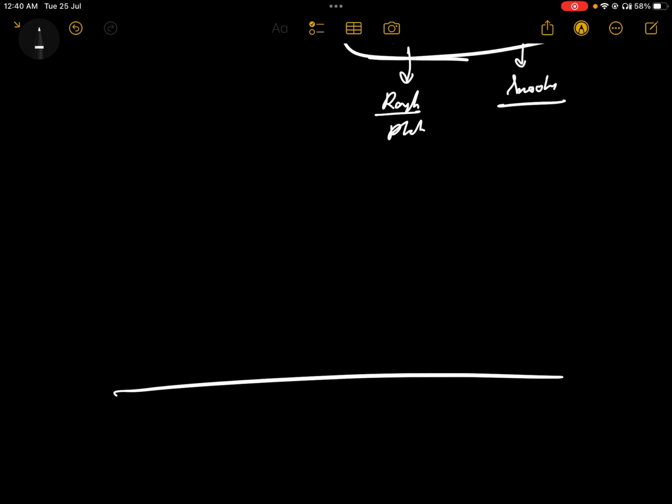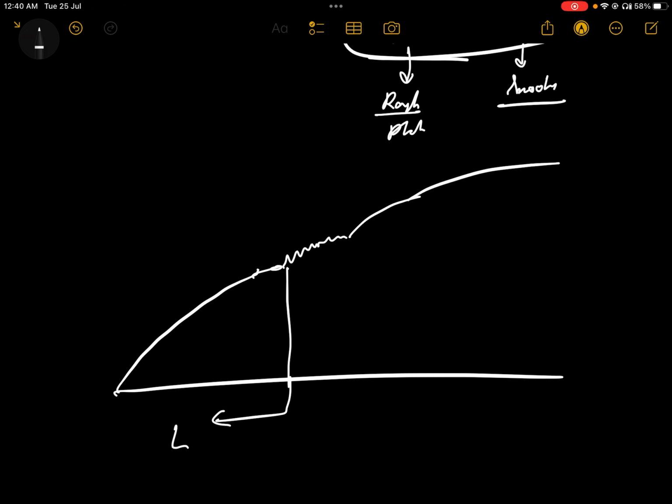If I show you the different flow regimes, I can show it like this: the boundary layer, then at some location x, when x increases, the Reynolds number increases, then it becomes a transition zone, and then it becomes fully turbulent. So here it is laminar, after that here it is turbulent, and here the flow becomes somewhat eddy.